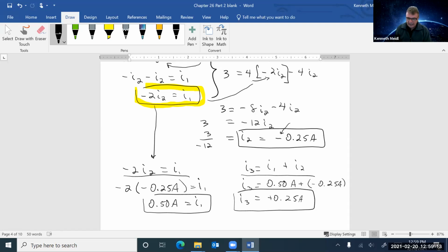Okay, but you can see here that very easily you can have 5 or 6 or 7 or 8 different unknowns, and those unknowns are your currents flowing through different parts if you have a lot of loops and so forth. Usually when you take some sort of circuitry class, somebody is going to remind you of Cramer's rule and using determinants to solve many equations and many unknowns at one time, so that you can do these things fairly quickly.